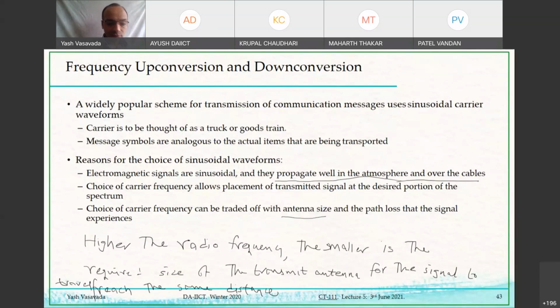And just roughly speaking, if you simply take the BPSK signal that we have studied, or QPSK, or M-ary PSK, or M-ary QAM, and if you just convert them into voltages, then we'll see very shortly that the corresponding signal has a frequency spectrum which is centered around 0 Hertz.